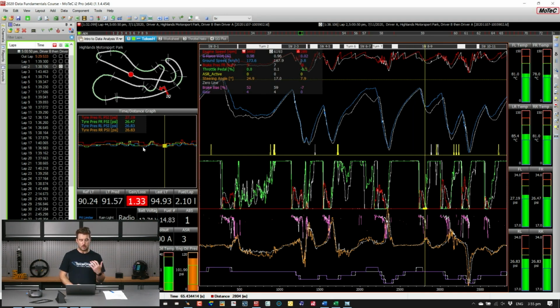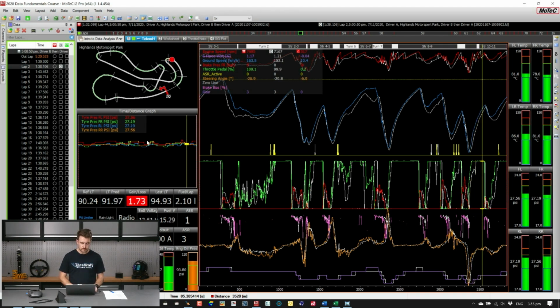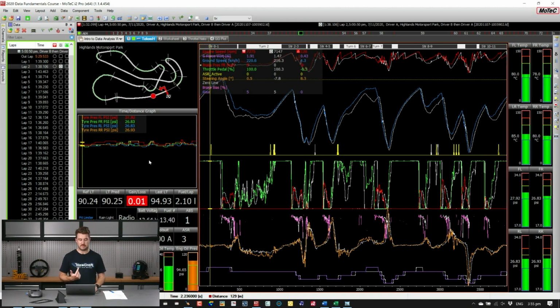So I always have used the same color convention for corners of the car, no matter what I'm talking about. If I'm talking about something like a damper or a tire pressure or any other sensor that's operating at either the front or the rear of the car. Front left's always, for me, red, front right's always green, rear left's always blue, and right rear is always yellow or orange. And the idea behind doing that is I don't really need to look at the legend. I can understand exactly which corner of the car I'm looking at without having to look up at the legend in the first place, which I find quite a big time saver when things are time critical.